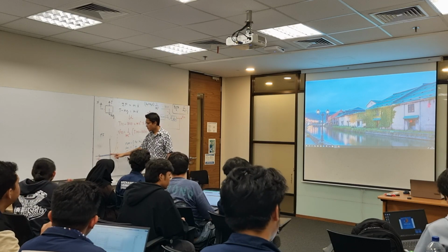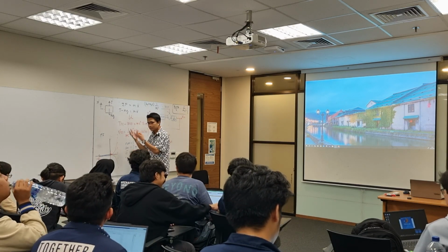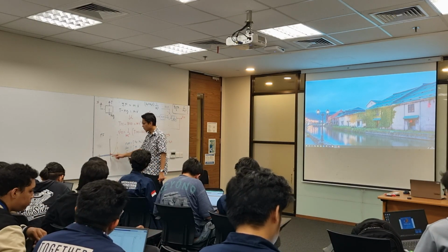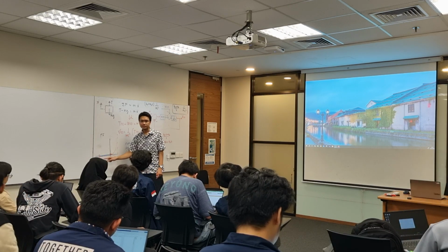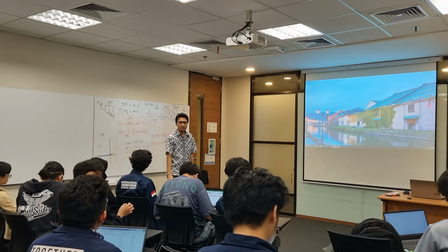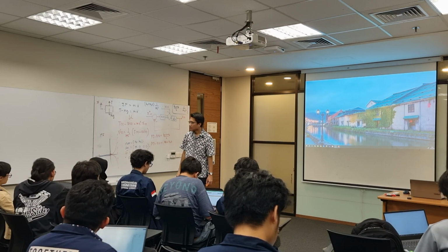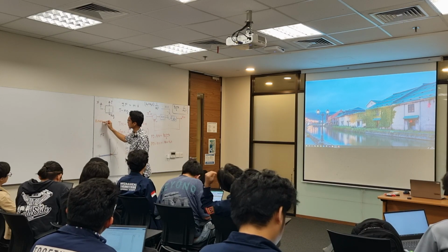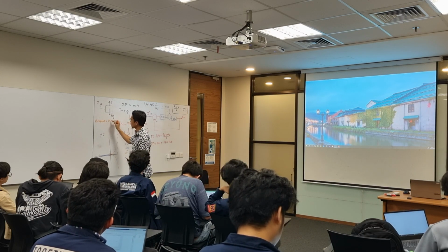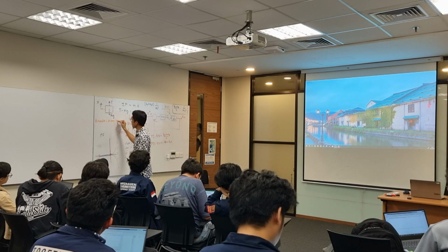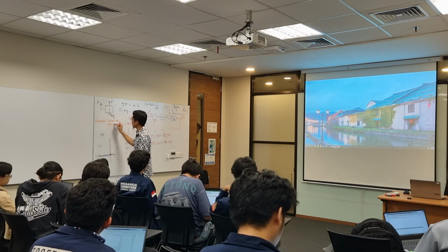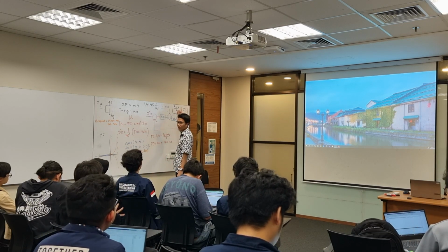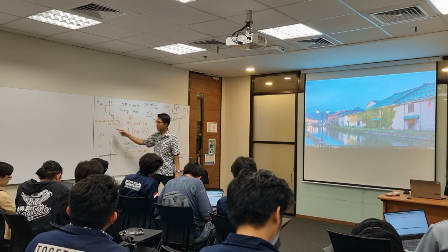So 2 of them will go to the right, and 1 of them will approach the open loop zero. The number of asymptotes is the number of open loop poles minus zeros. We have 3 open loop poles and 1 open loop zero, right? So in this case, 2 asymptotes.